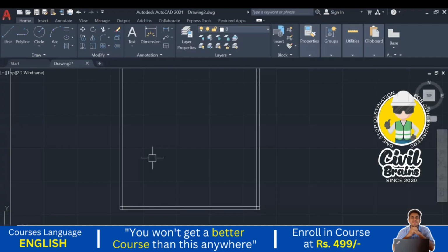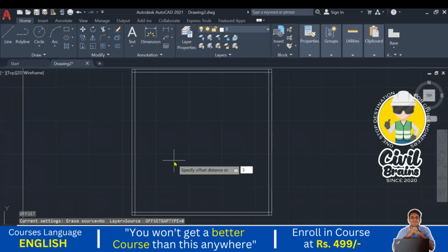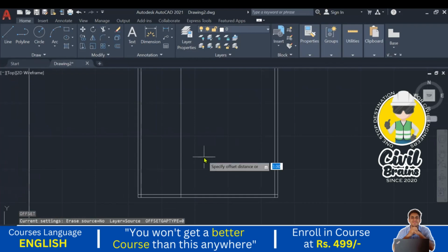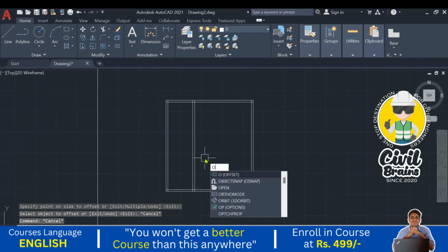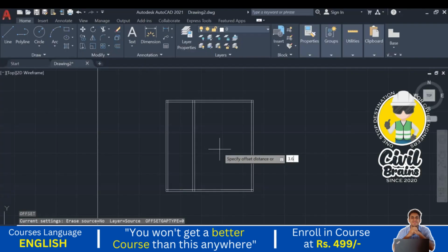I go to the AutoCAD. So offset 3 meter. Is it 3 meter? Yeah, 3 meter. Press enter. I just take offset, enter, offset 0.23. Press enter, wall thickness. How we have calculated the length and width, like that only we need to draw also. Next, we go to again offset, press enter. What is the dimensions? That is 3.6, 3.6, enter. We'll just draw this one, 3.6.